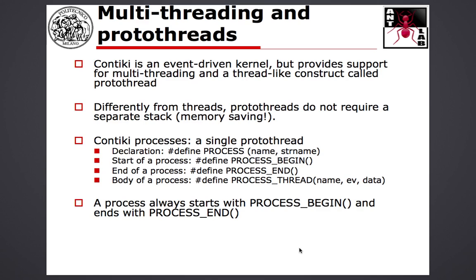But by implementing these proto-threads in such a way, of course you save resources because you do not have to maintain separate stacks, one for each thread. And if you think about the simplest application that you can write in Contiki, well, that is a proto-thread. So one application is a proto-thread. It can be either a single proto-thread or a collection of several proto-threads that run. We will see an example. Again, the easiest way to learn it is to see an example.